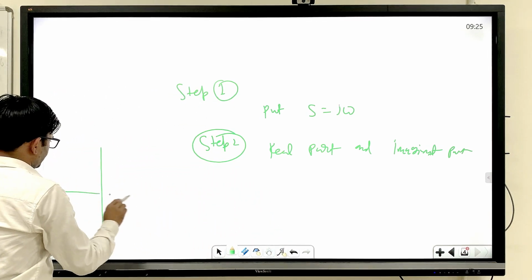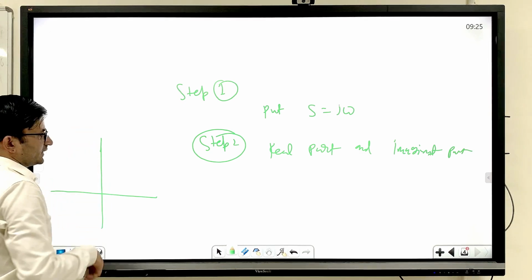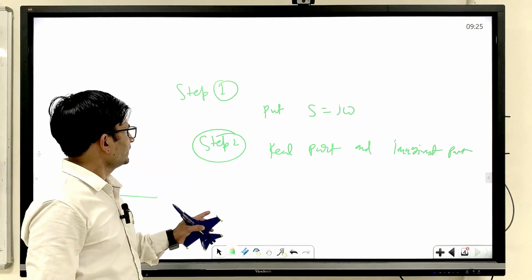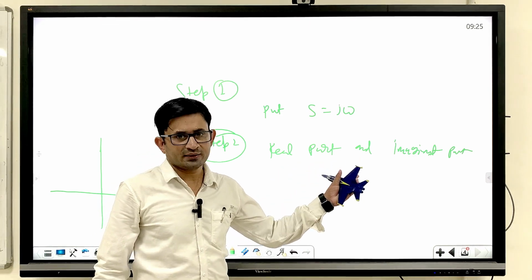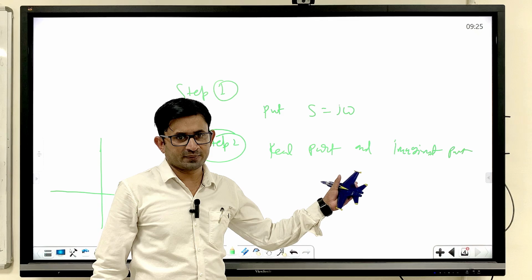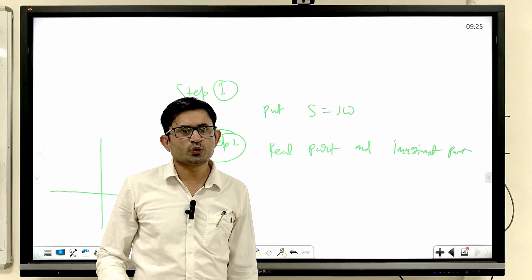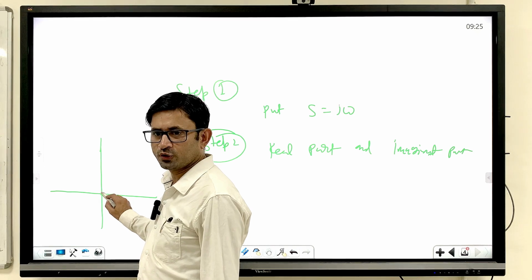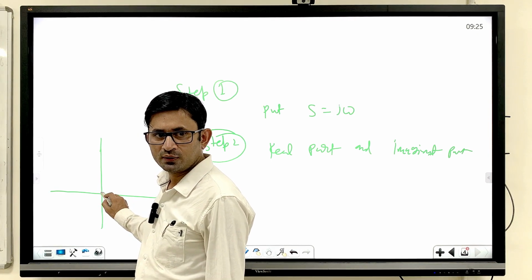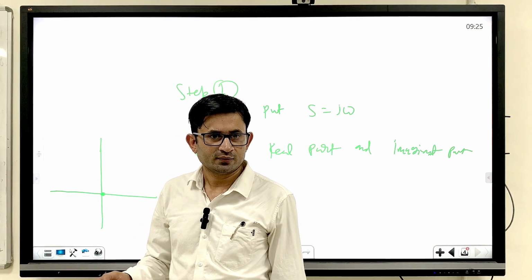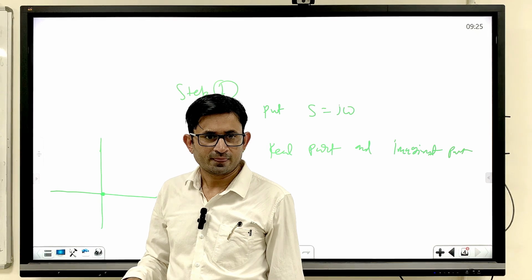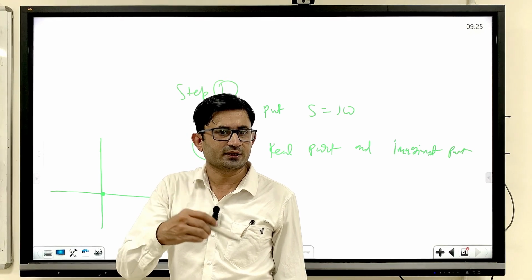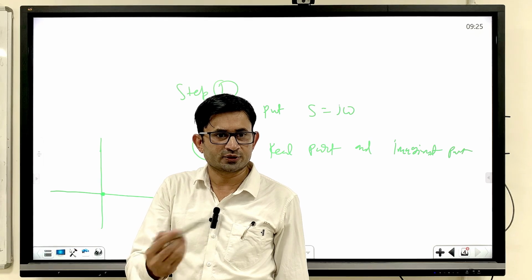See, in this complex plane, in this vertical line, up to where you can go, right? Plus infinity to minus infinity, right? So when you get the complex number by rearranging this, we will see. No, don't worry. Then put omega equal to 0, frequency equal to 0, and get the value, and then omega equal to infinity and get the value. Because you do not put the omega equal to minus, because ultimately the second part will be the mirror image of the first part.